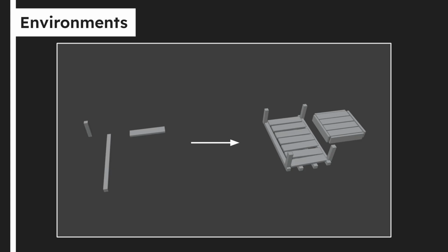And then instead of rendering this whole bridge in one pass, you'll have to do one pass for these pillars, one pass for these, one pass for these under rails. So if it's something static, I would recommend building it in Blender first. If it's something that needs to be a little bit more dynamic, maybe you need doors to open up or anything like that, I could say build it in engine.